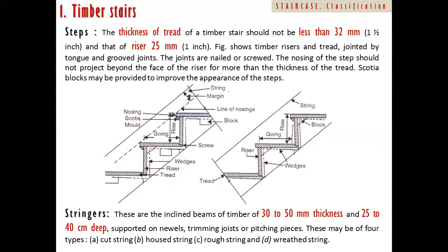more than that. Sometimes you might have seen in an amphitheater, where you sit, the tread will be more than 500 mm. So you just need to follow the minimum. In some places this dimension varies from 300 mm to 400 mm to 500 mm, and the riser is also 150 mm or more.